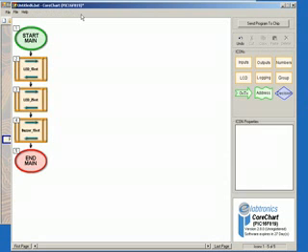ezCoreChart will automatically generate a test subroutine to test the green LED, the red LED, and the buzzer. To run these tests, make sure that the USB-P programmer is connected to both the computer and the eLab 16M controller board, and the battery pack is also connected and switched on.